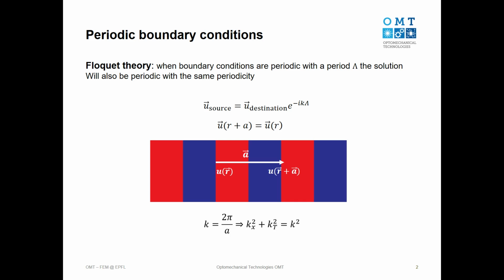So whenever I write, for example, kx in my simulations, I mean that, if this is the propagation direction, which is x, there are other directions, which I call transverse. This is the normal dispersion equation: kx squared plus the transverse squared should be our overall wave vector squared. So when we're sweeping the k vector, this means that we're sweeping this parameter, and when it's not equal to k, the rest is going into the transverse mode.